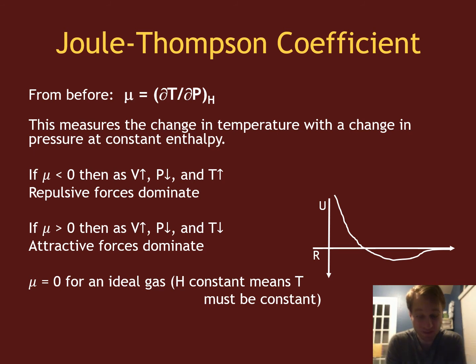This is a very tricky experiment to do to actually measure the Joule-Thomson coefficient for a gas, because holding enthalpy constant is not something very easily done. It takes very precise setups to ensure that there is no enthalpy change in your system. But if you do that, you can measure the Joule-Thomson coefficient for a material.